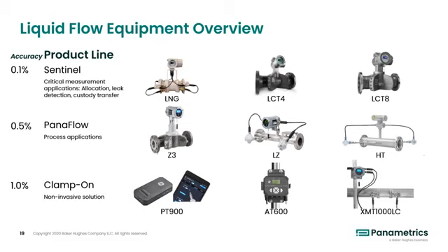The PanaFlow products are also wetted installations that provide a robust flow measurement in many applications. The PanaFlow HT on your far right is the world's first ultrasonic flow meter to be SIL certified. These are typically used on coker distillation, vacuum towers, or any other safety critical application.